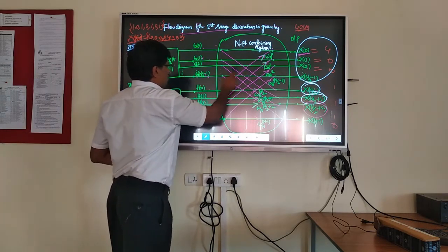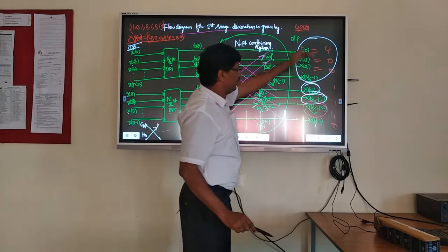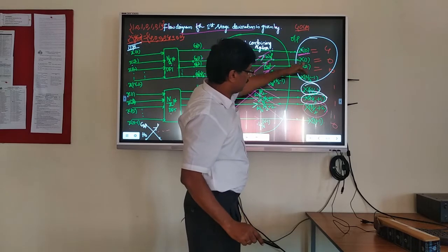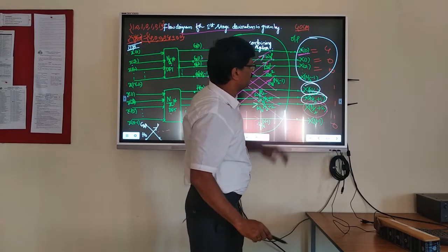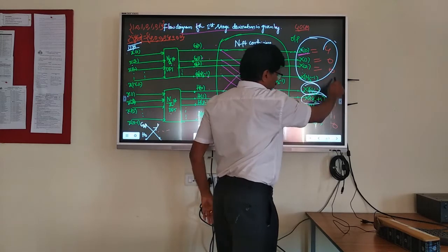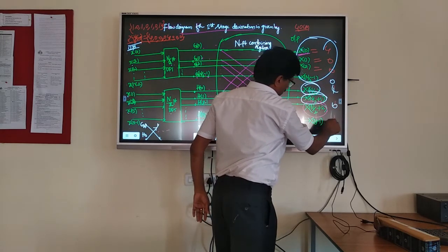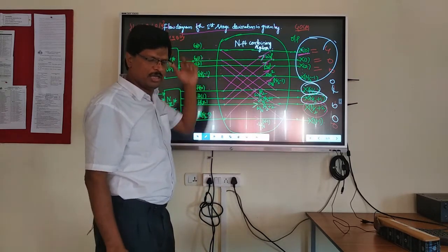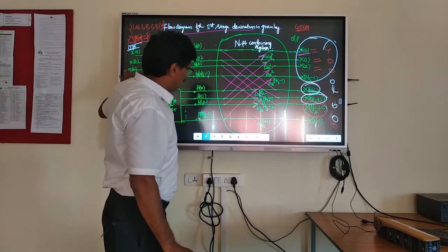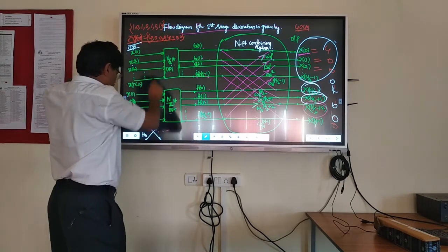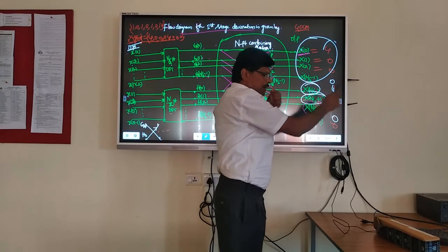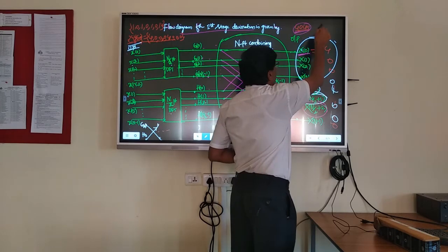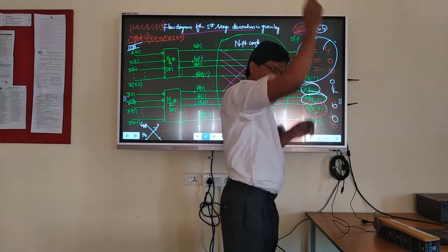Now draw 8 lines, straight lines. You will get outputs like this: X0, X1, X2, X3, X4, X5, X6, X7, let's say 8 outputs. Outputs are this one: 4, 0, 0, 0, 4, 0, 0, 0. Like this you will get it. Now, what's the difference between this algorithm and the direct DFT? Here also we are basically converting time domain into frequency domain only. We get the same output, but at the cost of 40 complex multiplications here instead of 64 in the direct method.